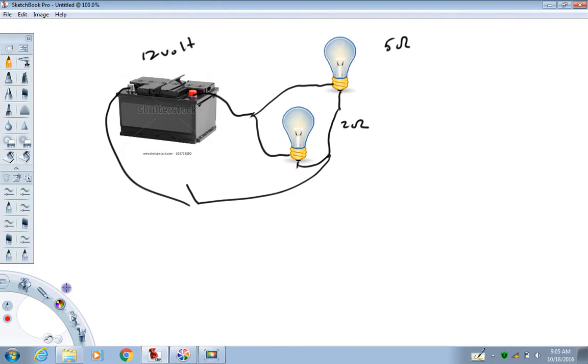If I were to color code the potentials, if you see my video on circuits, I like to do that. This would all be one potential up to this point here and here. The reason I know that is because this is presumably all wire made of copper. And if you think back or look back through my videos about conducting materials, conductors themselves are equipotentials. So if this is a 12-volt potential, this would all be 12 volts up to here and then to here. Now we would get a voltage drop because of the filament of the bulb.